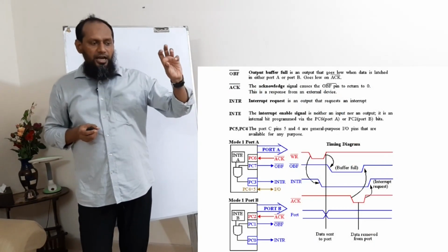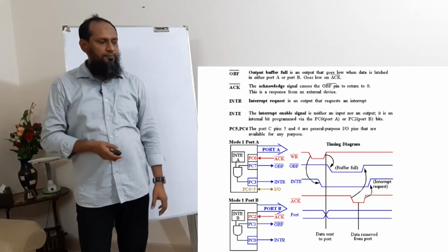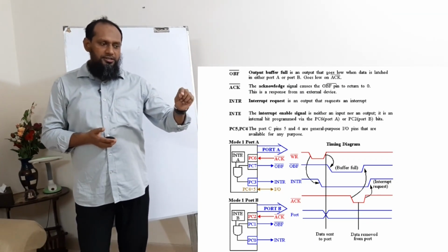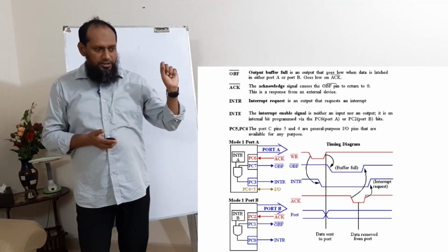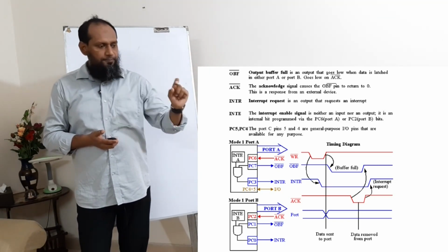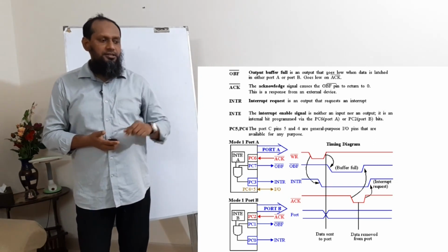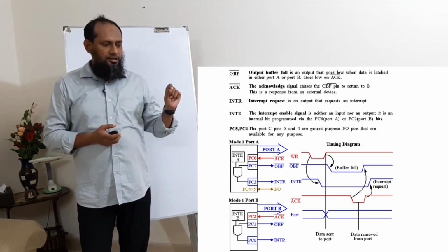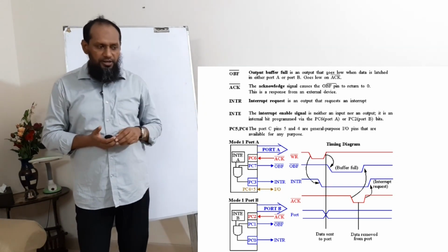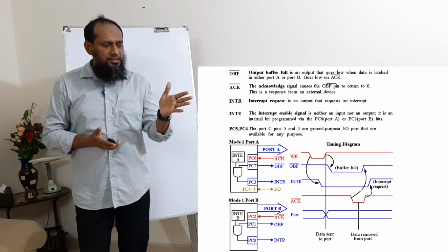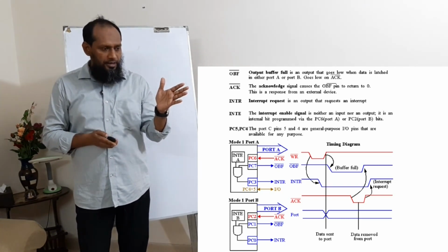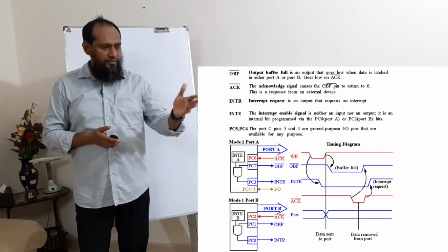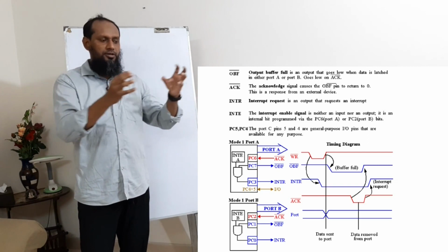Okay, so that is the timing configuration. You can find this timing configuration here. First, write, then interrupt generation, second interrupt generation, 3, write is deactivated, 4, it will generate the OBF signal to the printer, then it will receive acknowledgement on timing 5, then it will send data to the printer, and also OBF will become deactivated, and when the printer receives the data on timing 7, the printer confirms that it received the data, then the interrupt will be deactivated. Okay, this is how things work.